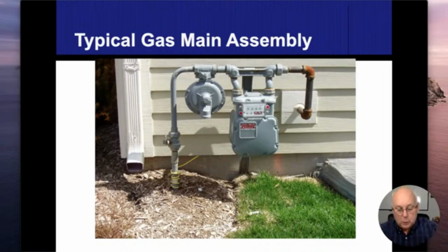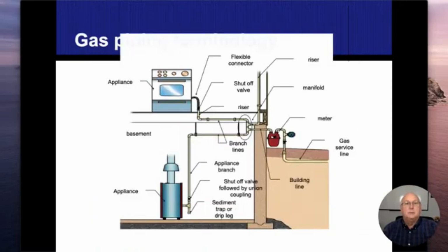All right. So short review. Gas comes in through a plastic pipe, switches over to a metal pipe. That wire that goes around it is a tracing wire. Our shutoff valve. We go to our regulator. We usually go from 4 pounds to 1/4 of a psi. And we go ahead and run our meters so we can pay our bills, and then it comes into the house and feeds our gas appliances that we have inside the homes.